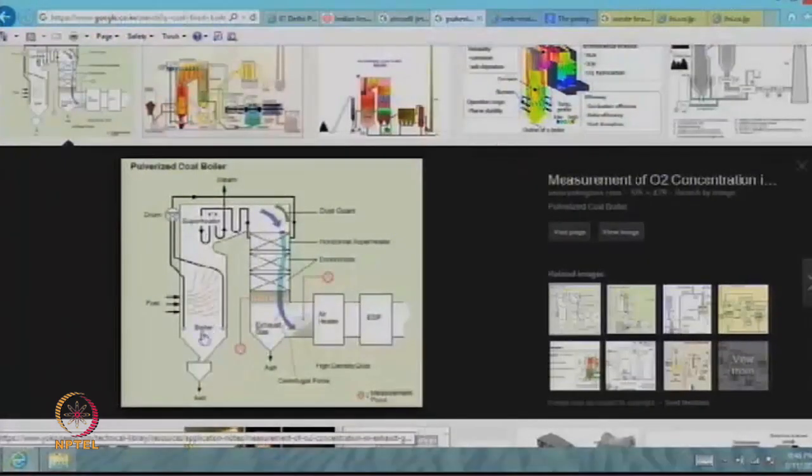That much air does not need to be heated by the burning of more fuel. We get a more efficient convection system. And then you have water being heated, then low pressure steam, high pressure steam, and finally here we get the highest temperature steam coming out of the boiler, which then goes into the turbines. Okay, so that is the practical rendering of this idea, and that whole design that you saw there is done simply because we are trying to minimize irreversibilities in the system. So that is the objective.